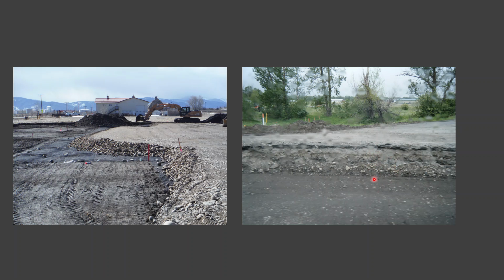And we have 4 different exhibits of strength going on here, where we have this weak compacted subgrade, a slightly stronger sub-base, a little bit stronger yet base materials, and then typically your strongest course is that surface course, whether it's concrete or asphalt.